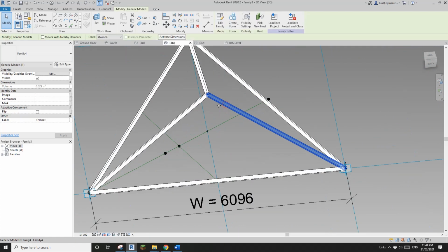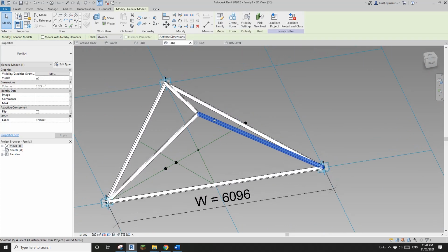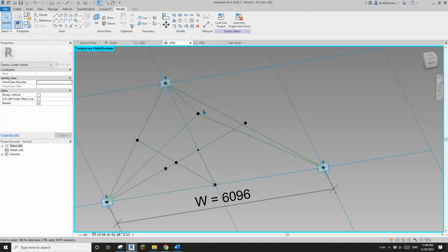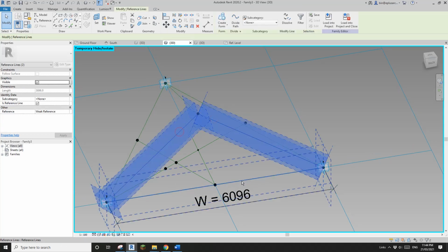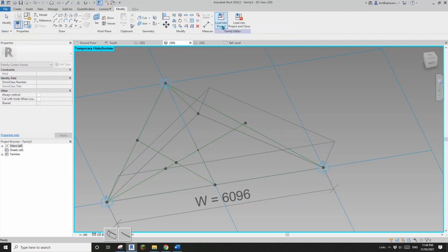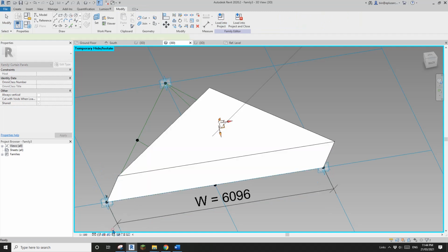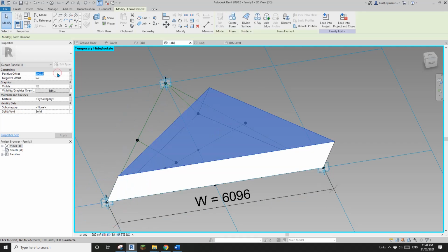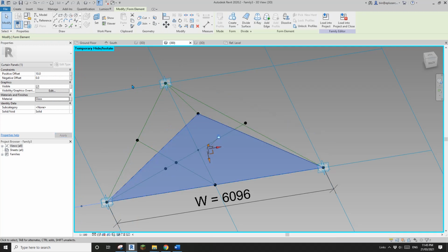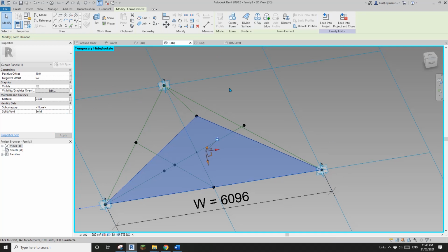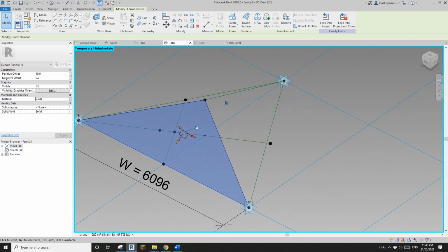And also we need some glazing. So SA, HH, 1, 2, 3. Create form, solid, typing thickness maybe 10, typing material glass. So of course you can create a material parameter if you want to, but I'm just too lazy.